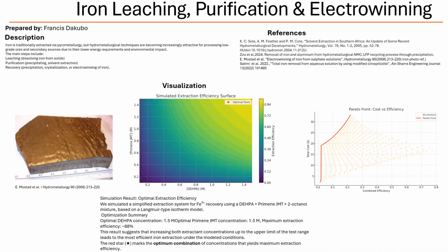Zinc calcine, that's the roasted zinc ore, right? Yep. But using zinc calcine for neutralization can lead to some zinc losses, and other metals can be lost too. So people have come up with modifications like pre-neutralizing with zinc calcine and then washing the jarosite to recover more zinc. They even tried two-stage precipitation to improve things further. Always trying to refine the process.